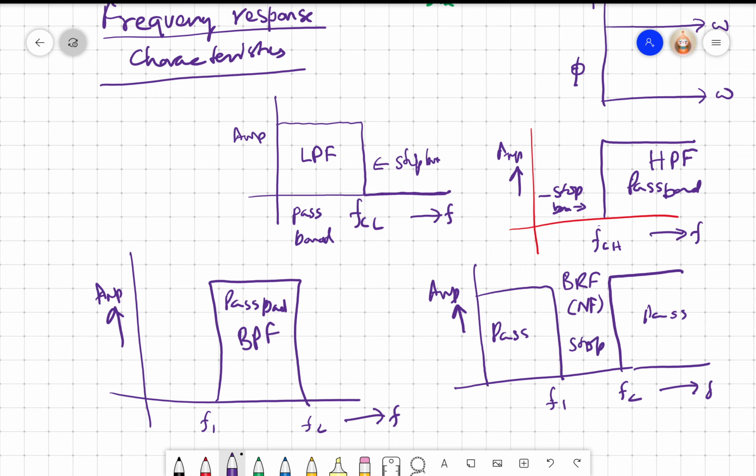So when I talk about the dynamic characteristics of a transducer, it simply means that my input is a dynamic input. When do I say my input is a dynamic input? When the input changes with respect to time. And there are two possible scenarios. One is that I have an aperiodic signal, it simply changes with respect to time, or the input changes periodically with respect to time.